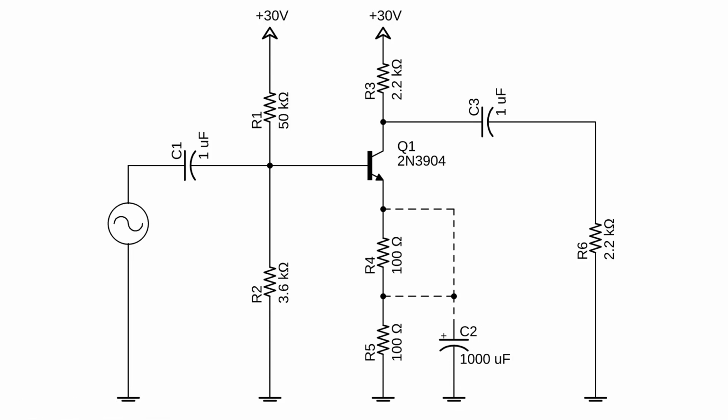Before we explore the performance of this amplifier, let's take a few minutes to consider how it was designed. Rather than going into the complete theory, I'm going to give you some rules of thumb that'll get you quite a long ways. For example, one of the first design considerations is the power supply voltage, which we selected to be 30. The next design consideration is the current, which we'll choose to be somewhere around 7 milliamps.